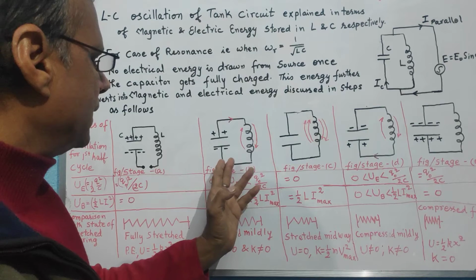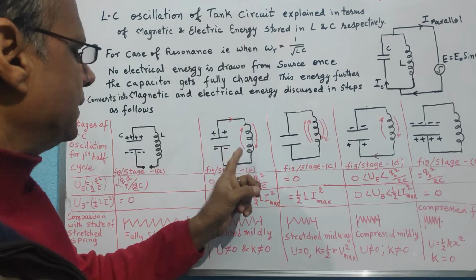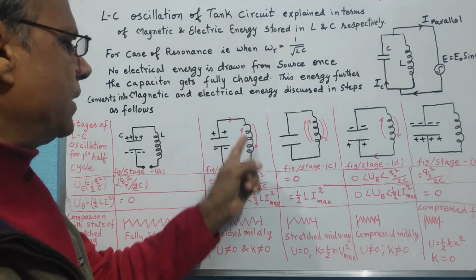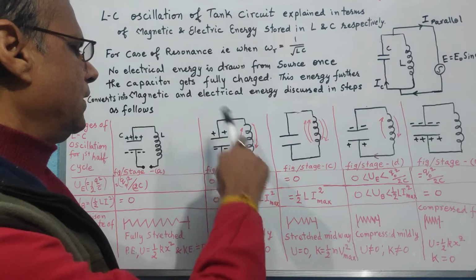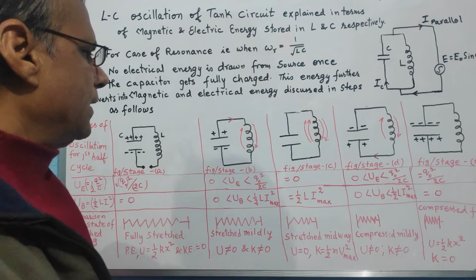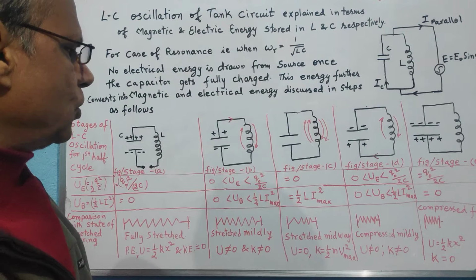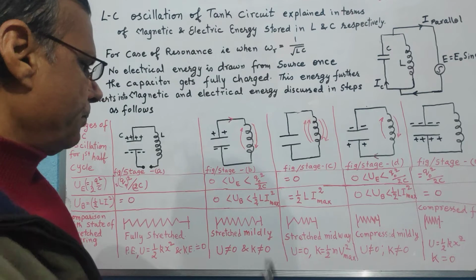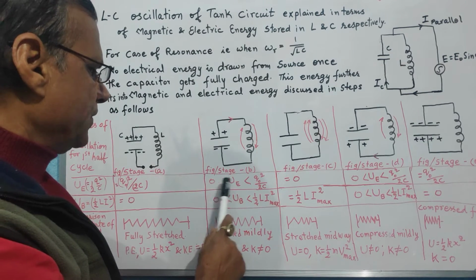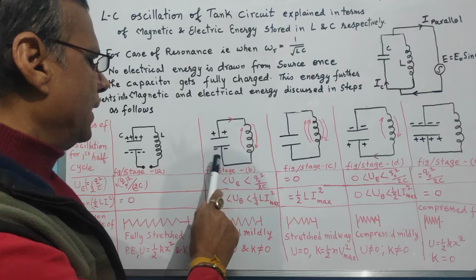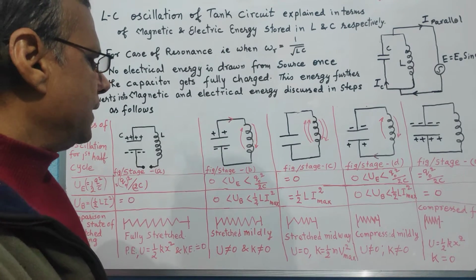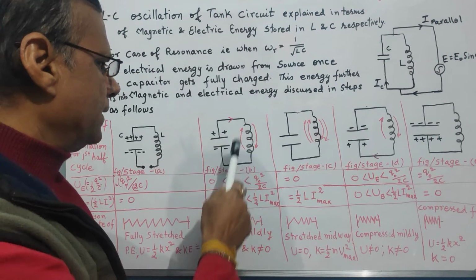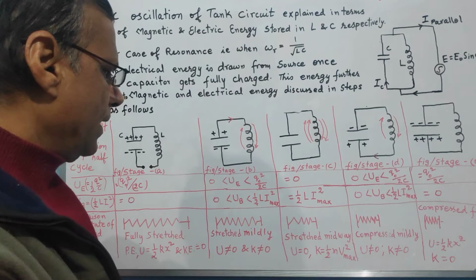Now the moment the circuit is completed, with the inductance and capacitor joined together in parallel, the capacitor starts discharging, and due to the discharge some current flows through the inductance coil. This causes some magnetic field to get stored in the inductance, so there is some loss of electrical energy stored in the capacitor, and equally the same amount of magnetic energy gets stored in the inductance coil.